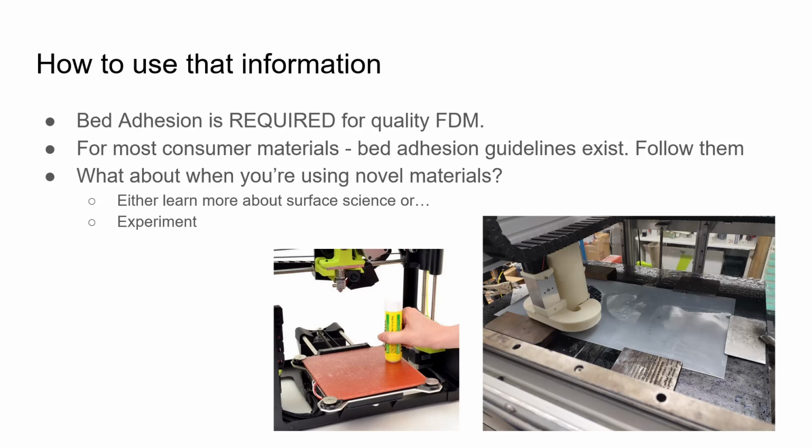But there are some cases when you're using novel materials, and you can't just Google things, right? I've run into that in my research, where I was using recycled low-density polyethylene, right? And so 3D printing with that, it was a bit of a challenge to have bed adhesion to the actual bed the printer I was using had. It didn't stick at all.